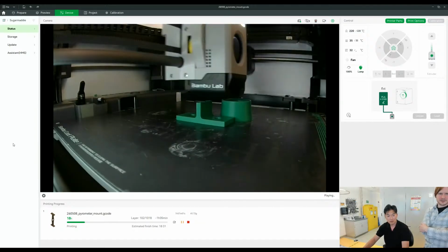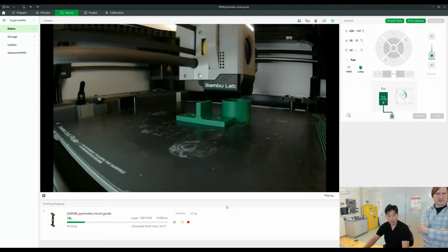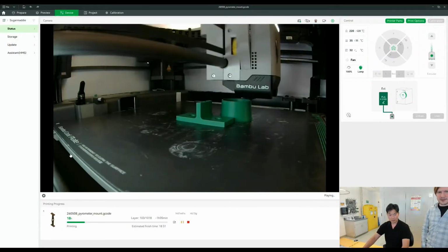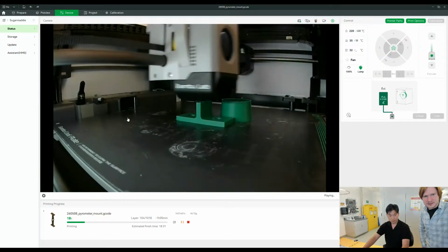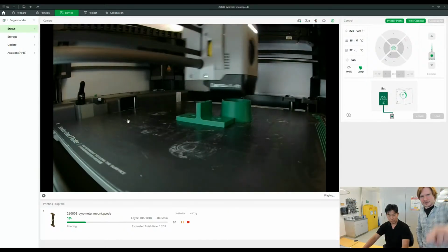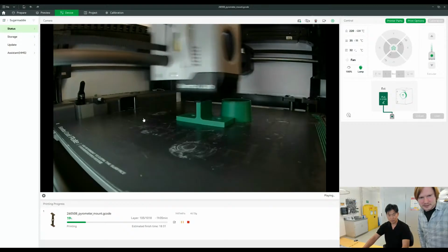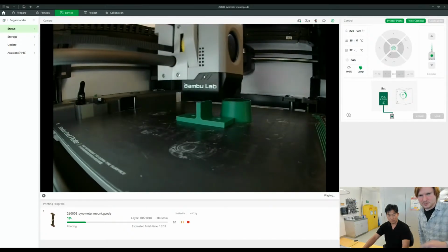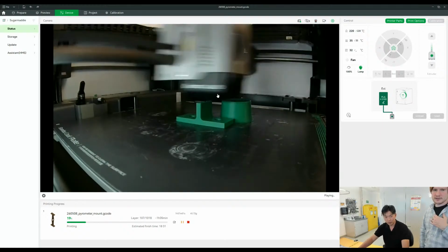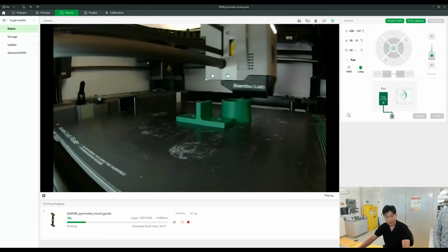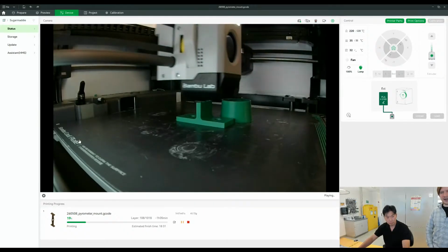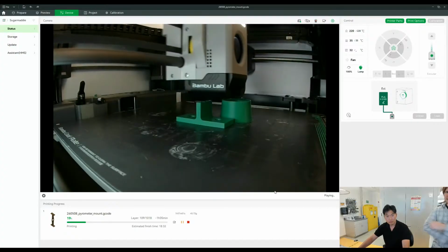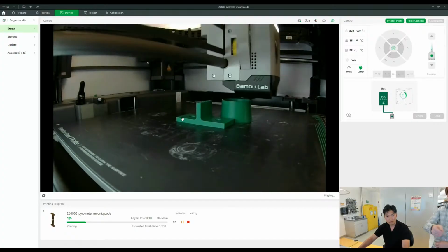You won't have all the noise issues you had with the DC relay. Well, we don't have any noise issues right now. Flipping on, because you're not flipping all the way on and off. AC is always already going on and off. So it's just sampling. You can have 0%, 100%, or in between, so it samples a little bit of each one. So the effective output is decreased or increased. The wave is always going up and down. You're not forcing a DC curve to go up and down. That's essentially how a dimmer switch works, like on your light switch.